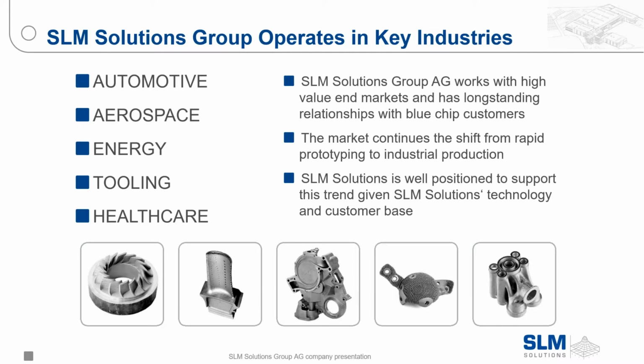That's 2 200s or 2 700-watt fiber lasers. SLM Solutions was the first company to introduce the twin optic setup, and then we improved on that with the SLM 500, which is up to a quad optic system. Again, with up to 4 700-watt lasers. The build chamber on that is 500 by 280 by 365. This is a production-based system.